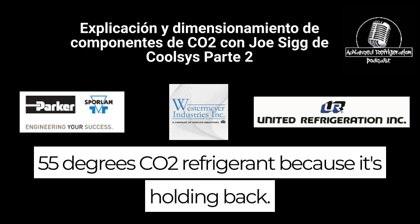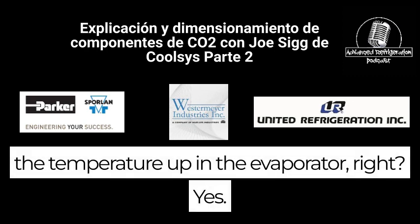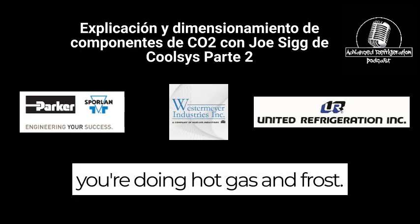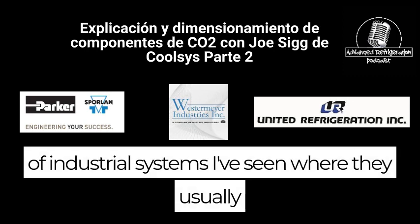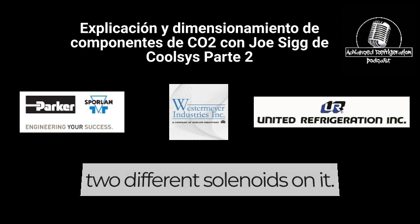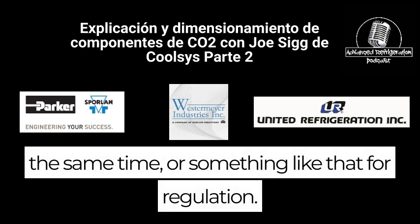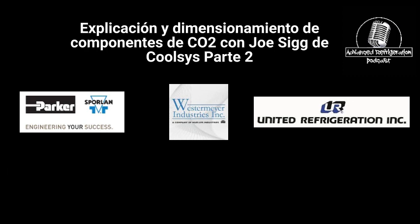So it's holding back, trying to keep 55 degrees saturated, which will keep the temperature up in the evaporator, right? Yes, defrost. So this is an essential item when you're doing hot gas defrost. This is exactly like a lot of industrial systems I've seen, where they usually have that Hansen regulating valve with two different solenoids on it. One for positive closing, one opening up, two at the same time or something like that for regulation. And then the other one for the fully open option. Correct. Yeah, wide open feature.